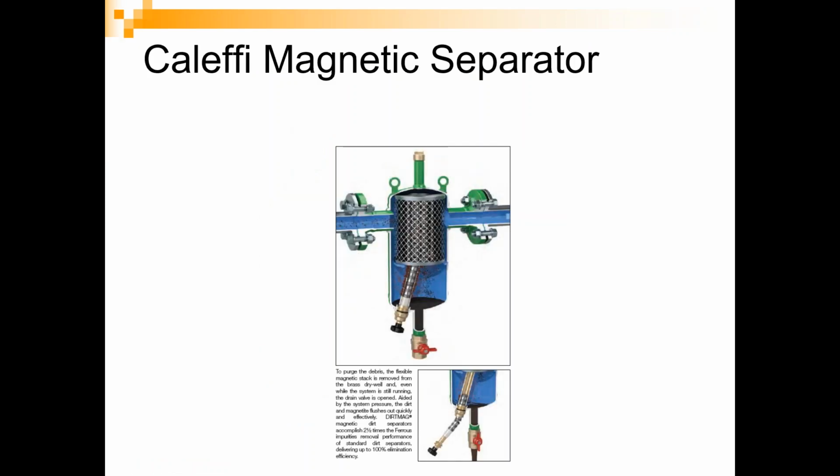One of the other things that's now available in our hydraulic separators, or also available in our air and dirt separators, is a magnetic separator option. This is basically adding a permanent fixed magnet inside of your hydraulic separator, inside your air and dirt separator, to make sure that we're pulling out any ferrous material from the water that's circulating through your line.